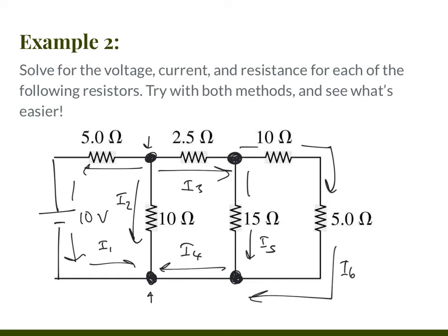If you're very good at systems or know how to compute them with matrices, Kirchhoff's law would be a great way to do this, because you're not going to have to write out that equivalent resistance thing a bunch of times. However, if you aren't good at systems and you're bad at matrices, don't know how those work with systems, have zero idea what I'm talking about there, then solving a 6 variable system is going to be really, really difficult. So I would recommend doing it with Ohm's law.